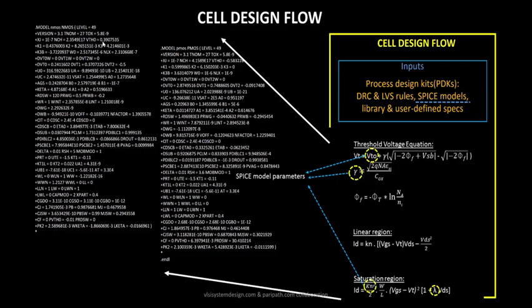It's over here. It's negative. It's positive 0.39 volts for your NMOS. Okay, so these are the typical spice model file. We call it a spice model file, and it also has all the capacitance values over here. If you see, it has CDS; all the ones starting with C are capacitances. Similarly over here, these are called spice model files, and those are again given by your foundry.